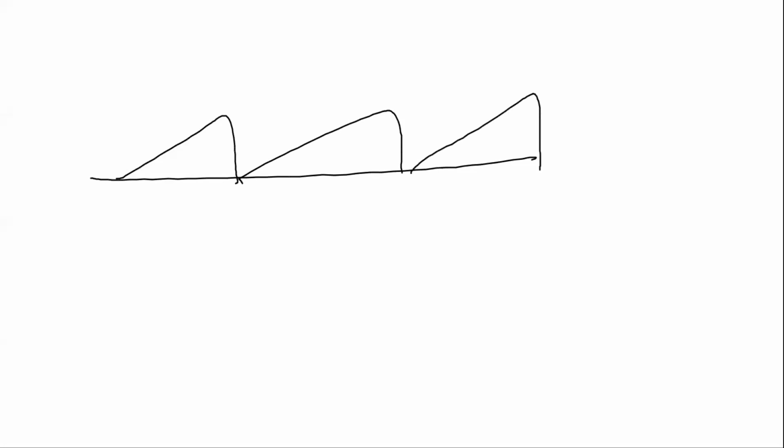So once again, I will share the whiteboard. Capture and compare: see, this is my carrier waveform. It may be in any form. I have drawn it like a sawtooth waveform; it could also be a triangular waveform. And this is the reference wave. Whenever I compare them and the values are equal, it can generate the pulse.